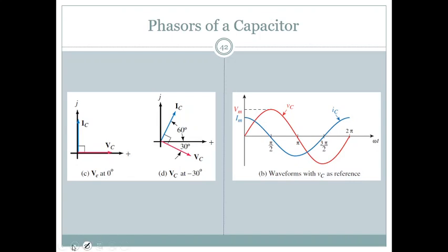So this is going horizontally, and this is going vertically up. Even if you rotate it a little bit, in whatever direction, as I talked about earlier, voltage will be lagging by 90 degrees to the current, or current will be leading by 90 degrees to the voltage. So this way you can draw the phasor diagram at any orientation.